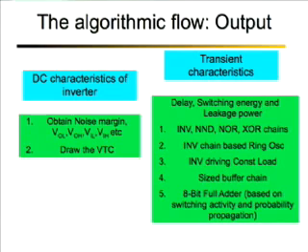And also, if the same capacitor has to be driven, instead of driving it with a single inverter, if we can size a buffer chain so that the delay is optimized in a big capacitive load, we do a sized buffer chain calculation of the constant load. And finally, we provide estimates of switching power and leakage power based on probability and switching activity propagation of an 8-bit full adder, starting from the device characteristics of the NMOS and the PMOS.